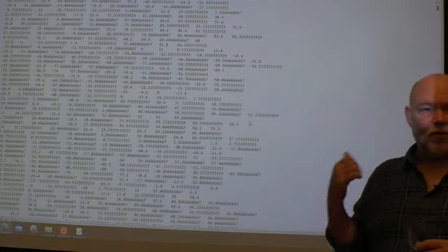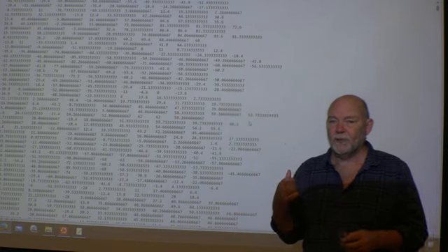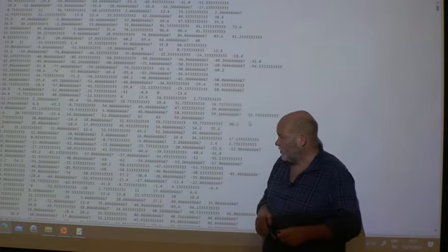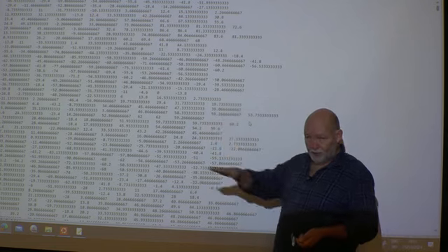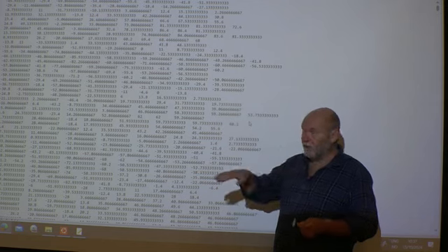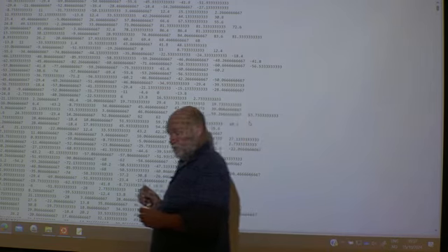But it's an incompressible simulation. Both water and air here, they are incompressible. We don't calculate the temperature. So we just use a reference pressure, 0 somewhere, typically on the surface, on the opening of the tank. Hence, yeah, you're going to get some negative values here. So what? It doesn't really matter what reference pressure we are using. But if you go further down in this file, all of a sudden you are getting quite big numbers. Then the water has hit.